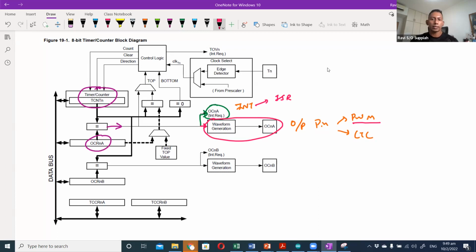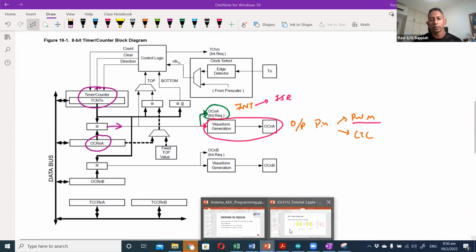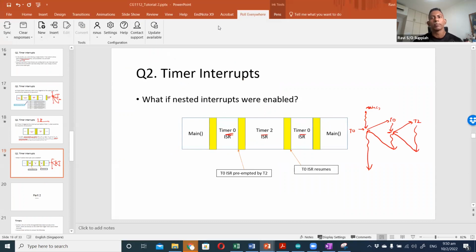So you don't need to put in the ISR if you don't need it. These are two parallel outcomes that start from the same trigger, which is when the TCNT matches the OCR register. This scenario will not affect the motor output if the motors are driven directly from the hardware itself.